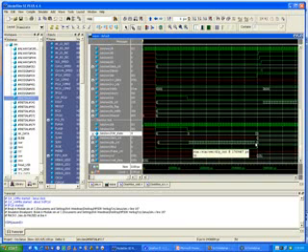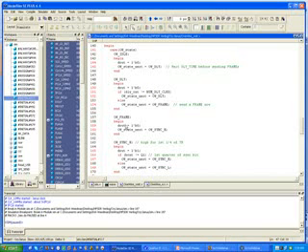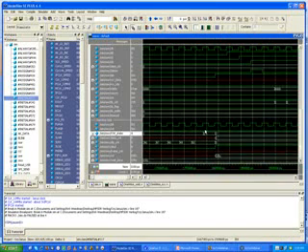As soon as it reached that value, the state machine says, okay, we're going to advance to state 2, which is a little hard to see here, but we'll zoom in. It went to state 2. So then what does it do? Well, when it gets to OW frame, it merely goes to the next state. I use this state to actually change some variables. So it just stays in that state for just one clock period, and that's what we see here.